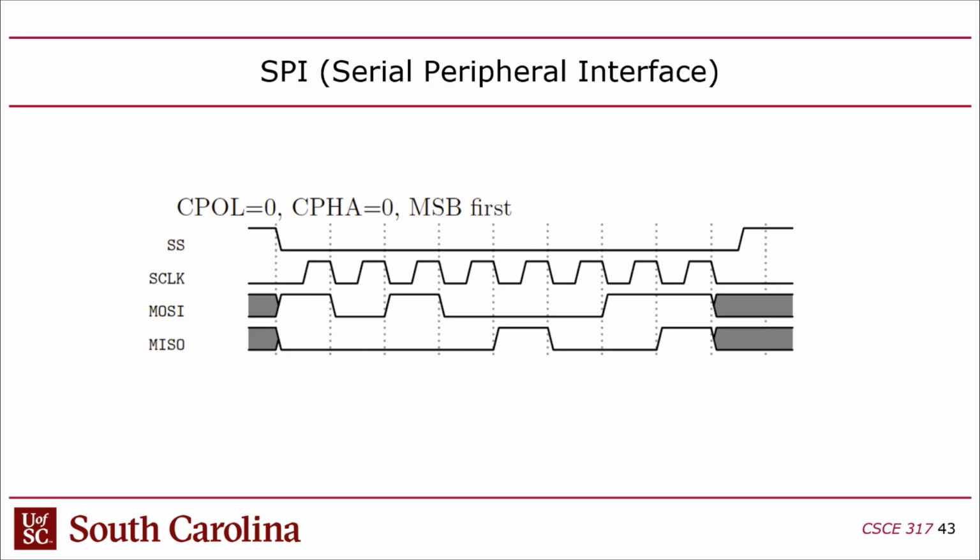It's important, by the way, because SPI is fast. It's not like PCI or USB Gen 2 fast, but it's fast. It'll do megabits per second, and I think you can probably drive an SPI channel up, in some cases, to hundreds of megabits per second. So it's very important to know when to sample, because there's so much capacitance on it, since it's usually a long, off-chip wire. You have to make sure that when you sample, the data is stable.